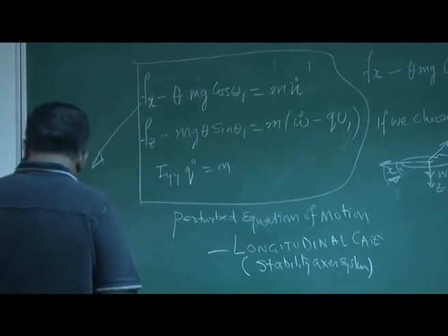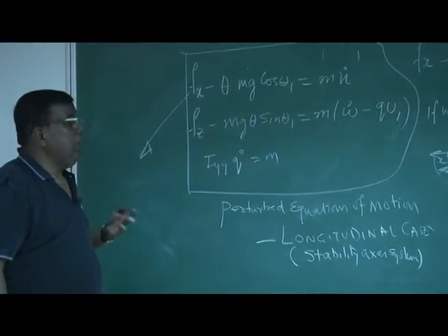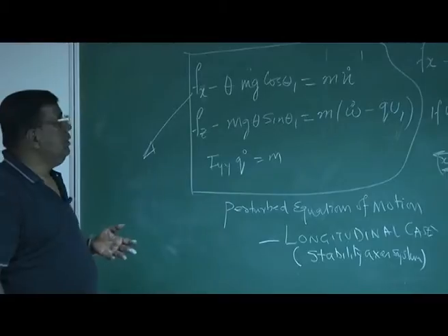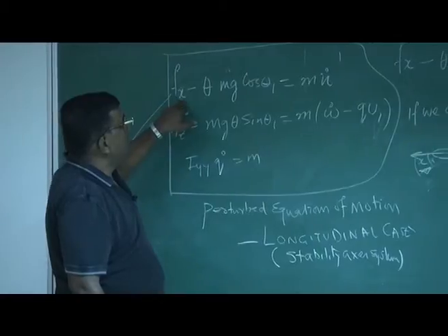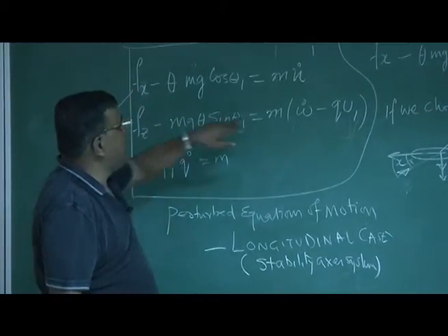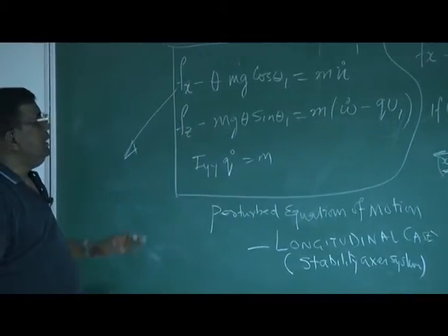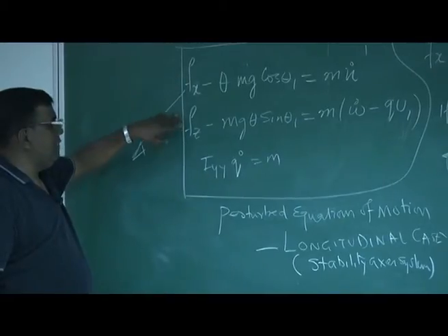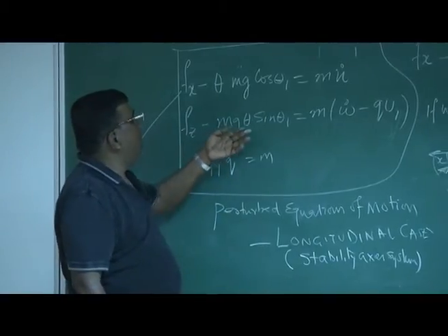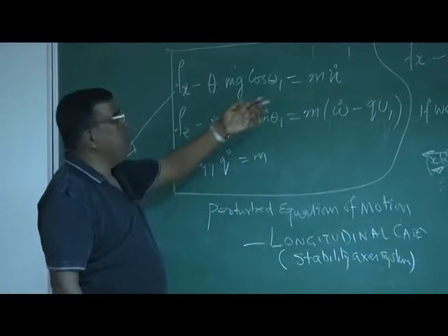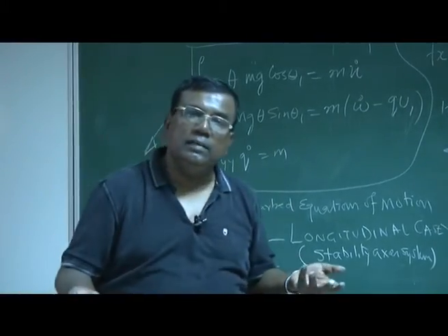So what is our aim? Our aim is to see how to analyze dynamic stability of an airplane. And you could see here, Fx is the perturbed aerodynamic force, and theta again is a perturbed quantity. All are perturbed quantities. What does it mean? That if there is a disturbance through Fx, Fz, or a moment, then we see how the perturbed quantity q, or here w, or here theta, or u is going to vary. If it comes down to 0, then we say it is dynamically stable.